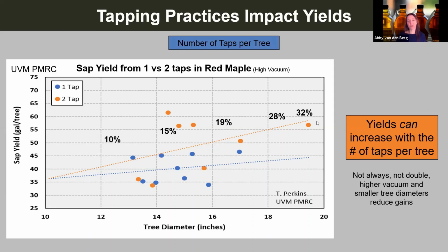And question from Stu. It is my understanding that tapping below the lateral is not an option on gravity. And Stu, you are definitely right about that. Tapping below the lateral is a really bad idea on gravity. I do not recommend it. If you want to try and give yourself a headache, you can try, but it will not work on gravity, at least not very well.